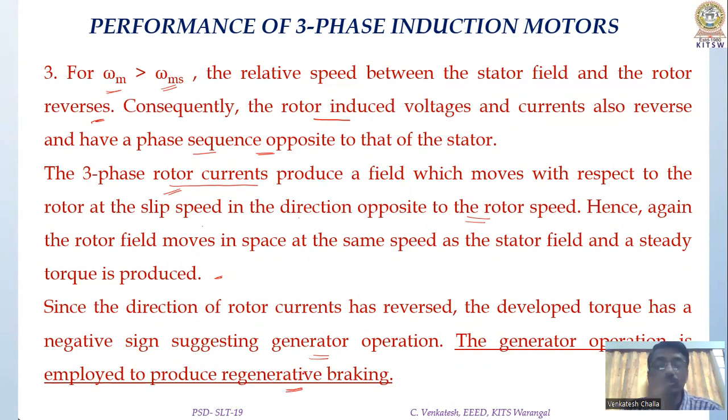So whenever we want to stop the motor, the back EMF or the energy stored in the motor can be supplied back to the source by making the rotor speed greater than the synchronous speed, and hence the motor operates in regenerative braking mode.